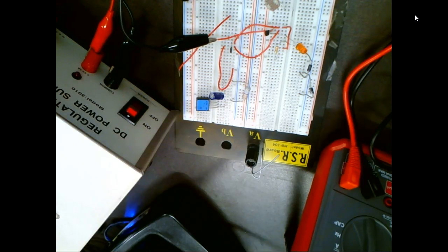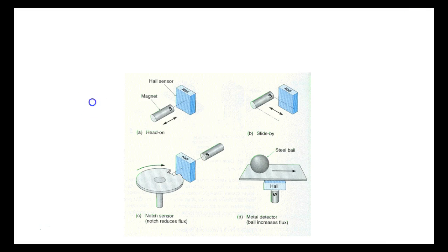It can't sense metal, but we can simulate it because we know metal concentrates magnetic fields, right? You understand? So coming through here is what we're saying, okay, it's sensing a metal ball. Well, it's not sensing the metal ball. It's sensing when the ball rolls across that magnet, the magnet concentrates the field through the ball and causes that Hall effect to sense the magnetic field change, right? You understand? When this thing right here is flopping around right here, the Hall effect is going to output a little dip every time it makes a rotation, right? You understand? Or we could use a magnet.